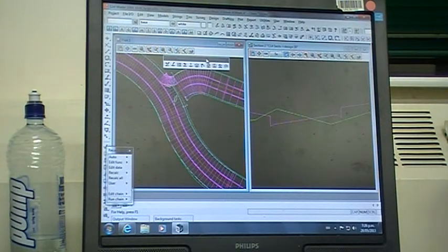There's two main design criteria for stormwater systems, certainly in Auckland at the moment. We either design using the rational formula. Has everyone done a hydraulics paper or had some kind of... Okay, so to calculate design flow, it either uses the rational formula, or under the old ARC they had a system using SCS curves, which was in TP 108.